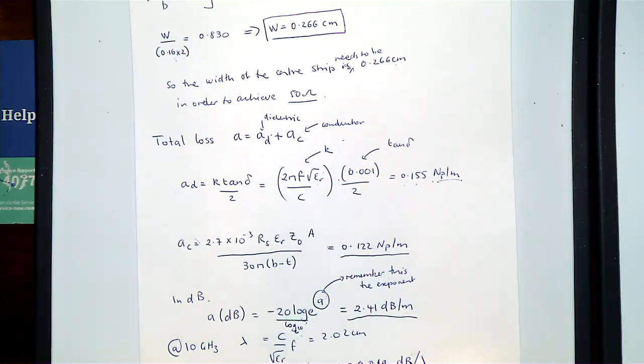And it turned out to be roughly 0.05 dB per wavelength, right? Which generally is pretty good, right? Usually on some chips or other types of structures that you build, especially at higher frequencies, you might be getting 5 to 10 dB per millimetre loss. Okay?